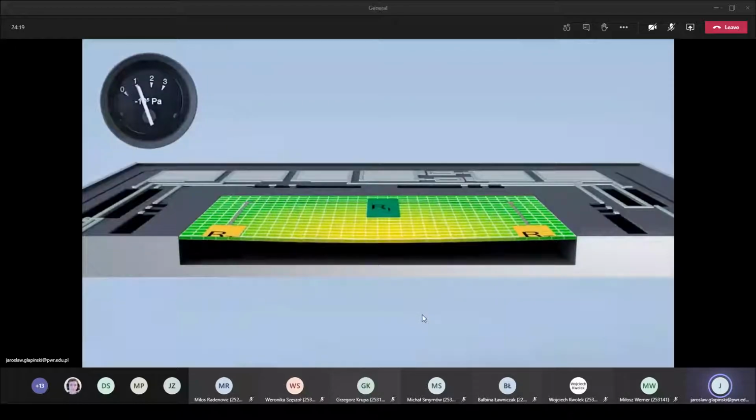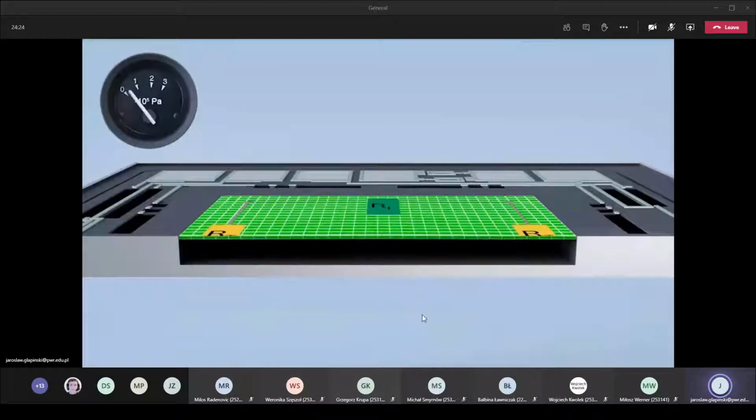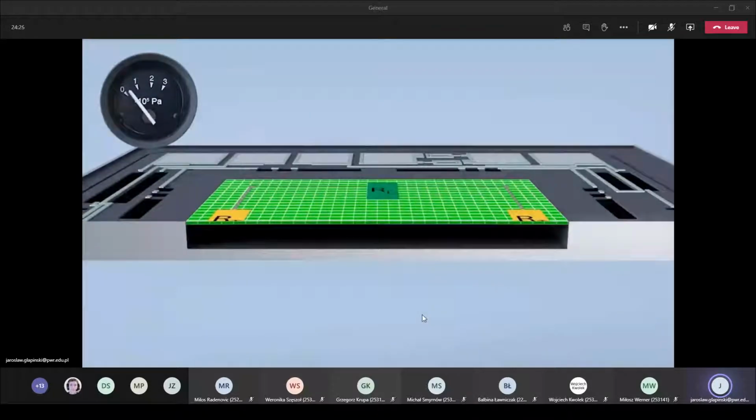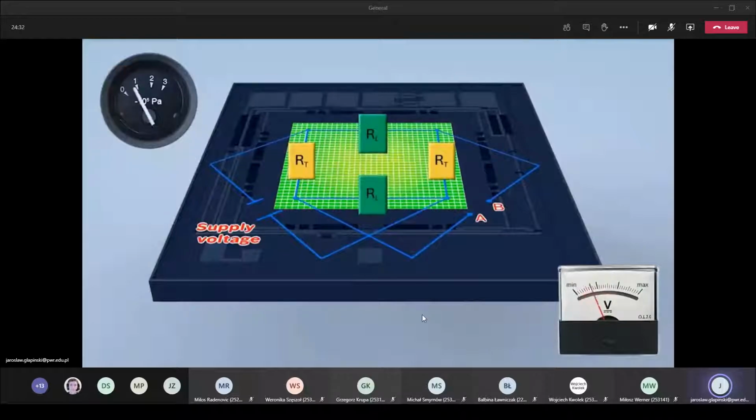Changes in pressure cause the membrane to change shape. An electrical voltage proportionate to the amount of distortion is created at the resistors. The change in voltage is the result of the ambient pressure. In analog sensors, the typical signal voltage generated is between 0 and 5 volts.